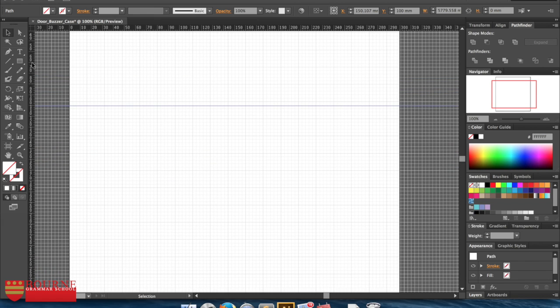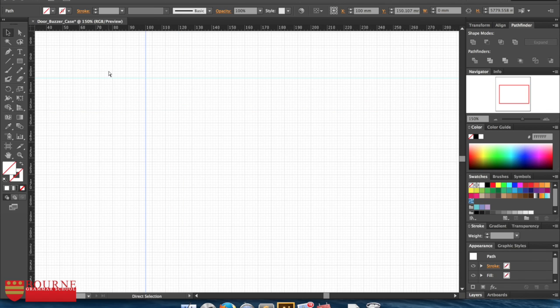I'm now going to click over here and drag, and I've got another guide, a vertical guide, which I'm going to place. Now on this vertical guide the Y coordinate doesn't matter, but obviously the X does. So again, I'm going to set that to 100 mil. And now I have my guides all set up, intersecting at 100 and 100, which is what I want. Let me zoom in just a little bit on that.